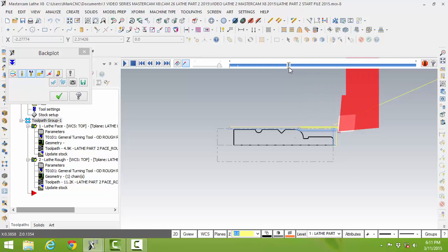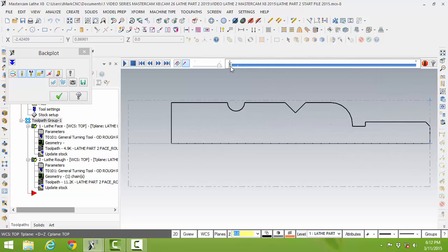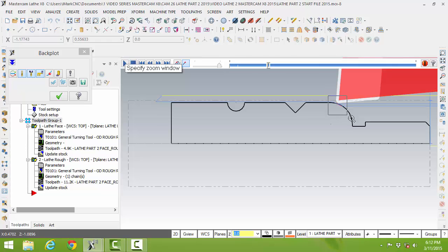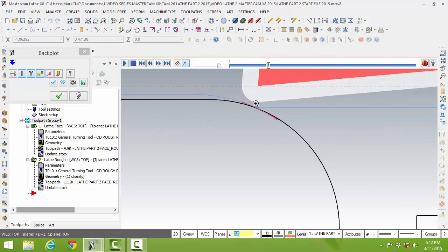And what is the depth of cut set to? Correct, 25 thou, and with a feed rate of 10 thousandths of an inch. Let's make this fit a little bit closer and watch it again up close. You can see the tool come in here. And we talked about that blue part. Let me zoom in on here. You can see, watch the edge of the tool. That's what we're cutting. So we're looking here at the intersect where these meet. And that's what this blue path is about.